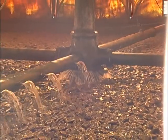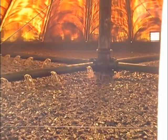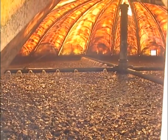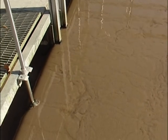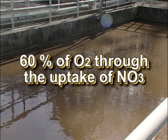For fixed film systems, it is important to have adequate ventilation to maintain an aerobic environment. It should also be noted that in facilities that have an upfront anoxic zone for denitrification, there is a beneficial return of oxygen through the uptake of nitrate. This beneficial return can be up to 60% of the oxygen required for nitrification.